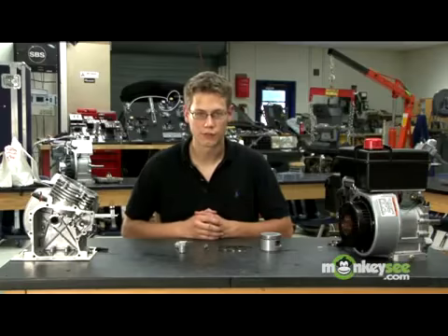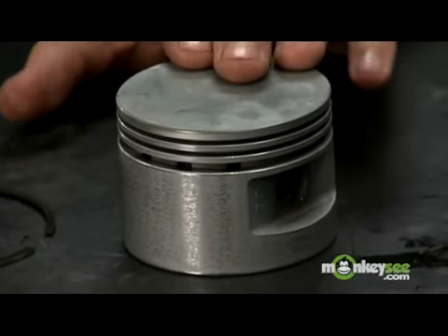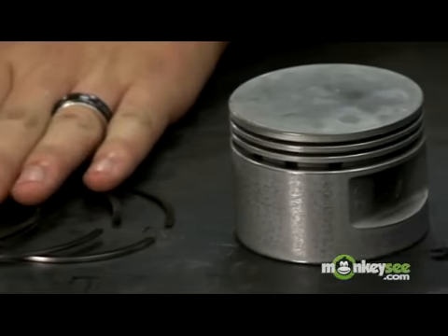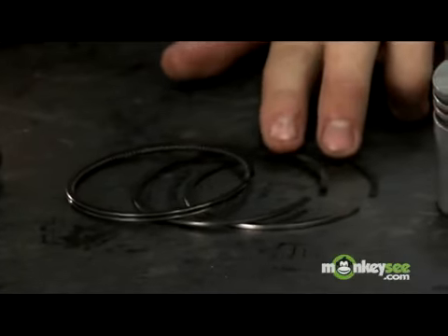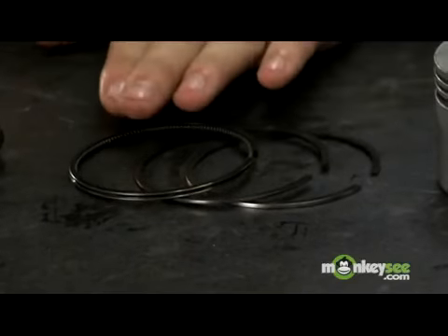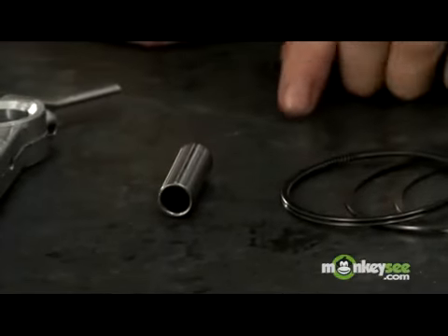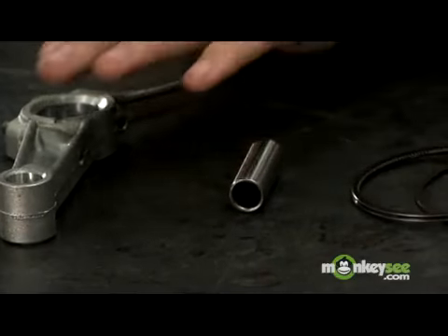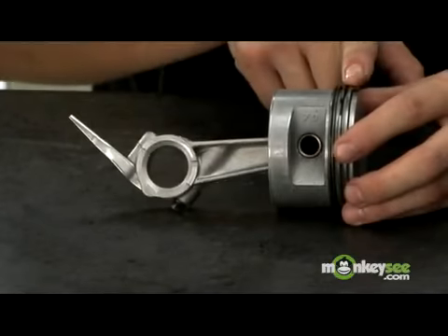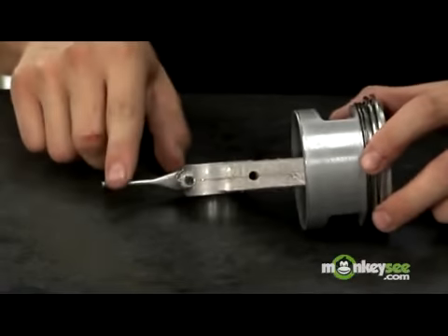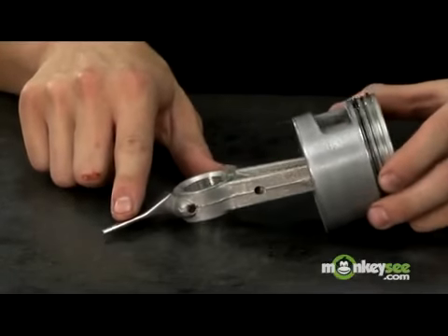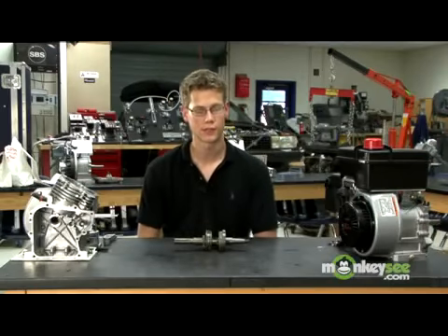The piston consists of 4 main components: the piston head, the piston rings, 2 of which are compression rings, and 1 special ring used to hold oil against the walls of the cylinder, called an oil ring, the pivot bushing, and then the piston arm. And attached to this arm is an oil thrower, which is used to disperse oil inside of the crankcase, maintaining lubrication throughout the system. The second component I'm going to illustrate is the crankshaft.